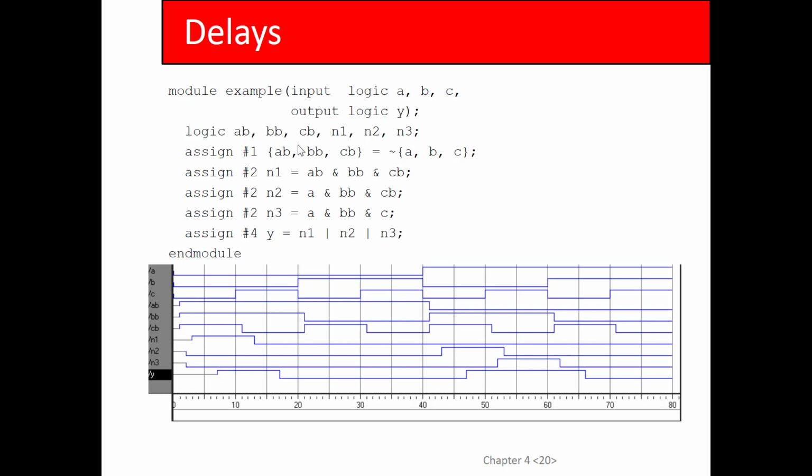And with regards to behavior, all of the logic happens in basically an infinitesimal amount of time, epsilon time. In other words, if something over here changes on the right-hand side, the left-hand side is updated immediately. I mean, not 0, but epsilon. Any amount of time beyond 0 will cause the update to happen. You guys with me? Which in reality is unrealistic because real hardware doesn't work that way. There's a propagation delay, as we learned. But we don't care about propagation delay when we do this kind of simulation.